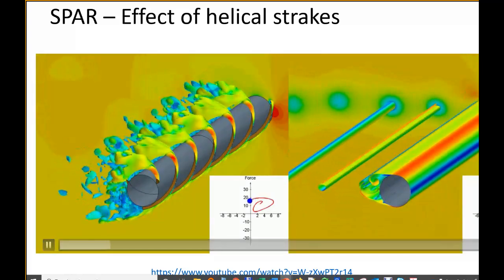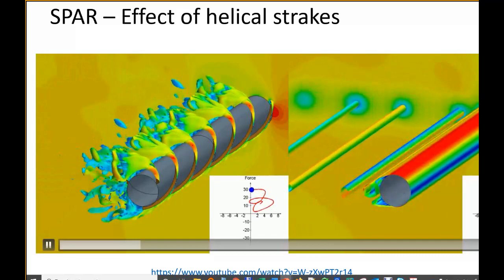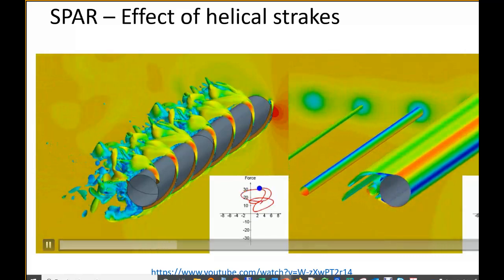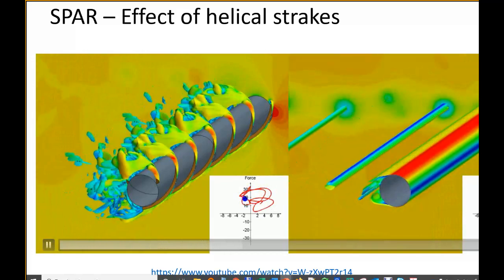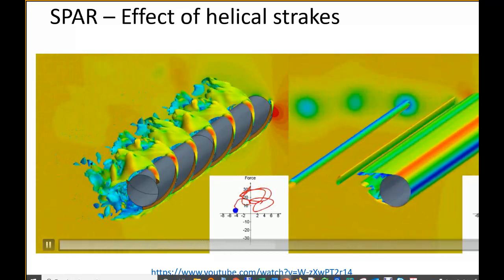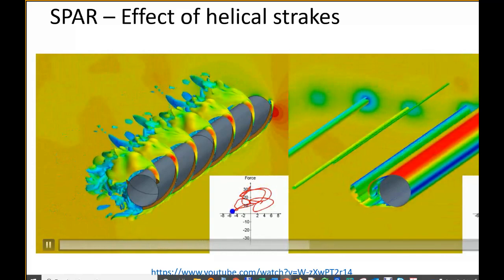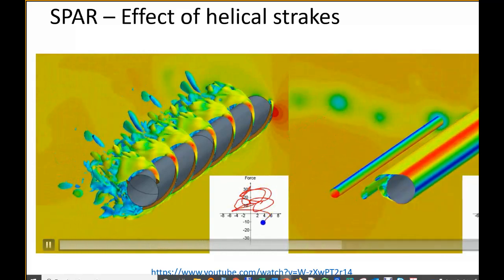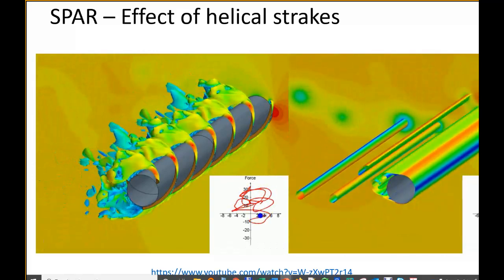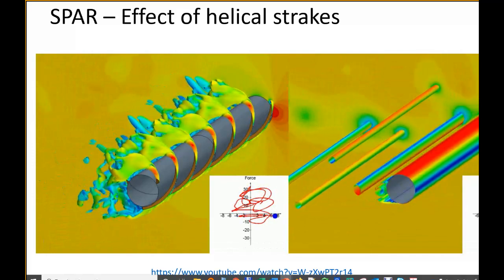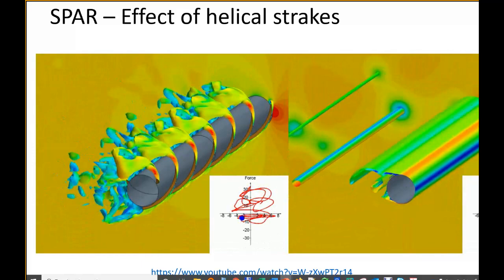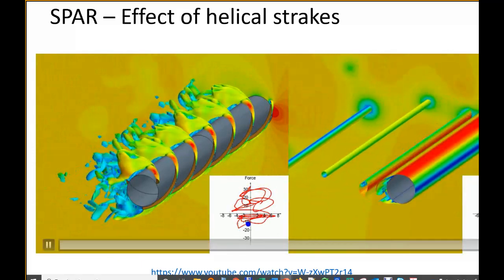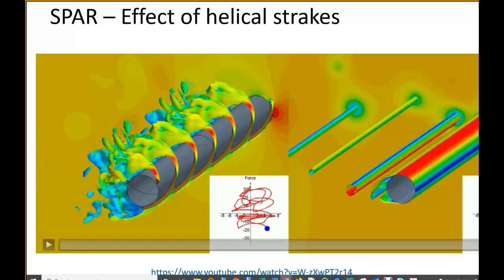Here you see the detachment, okay, and the force that it is causing, and you see the oscillation in the force due to the vortex releasing up here, down here, while here you have a more chaotic pattern. Okay, it's not cyclic. Remember, when you talk about vibration, you talk about mechanical components. Every time you have an oscillation, you have a problem with resonance, right? Because here you have a very uniform excitation, with a very uniform period.